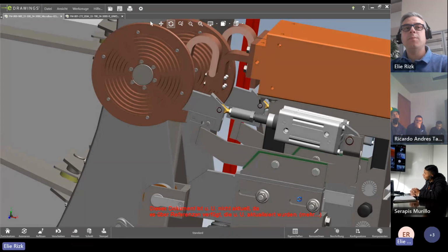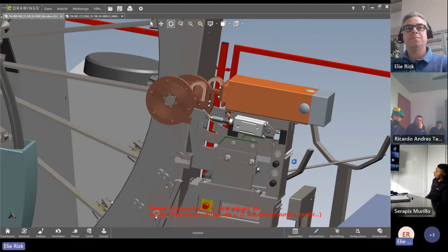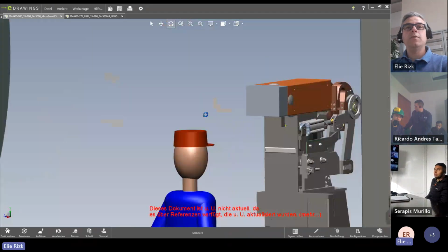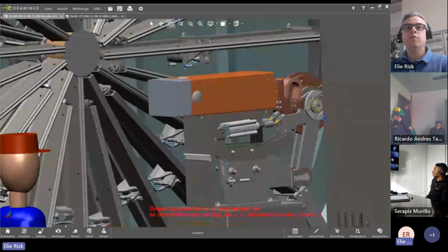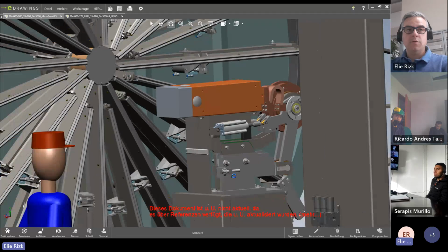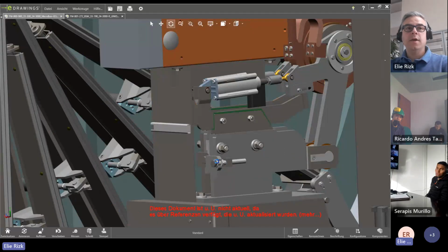So you need to move the complete arm a little mechanically. I mean, you have to move it. And normally you don't move the welding roller arm, but you move the contact roller. So with this screw here, you can move a little in front or back.